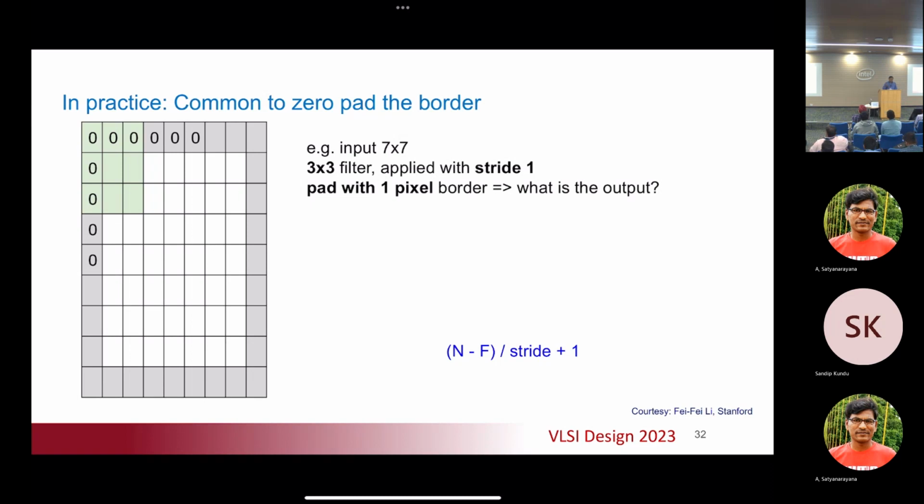So including normalization, including nonlinear activation, and including the Softmax layer, the very last layer of computation, which I didn't describe, I'm going to describe that. It's about 10% of the computation. So if you want to accelerate something, this is what you want to accelerate. Okay. If you have more resources, you would of course accelerate the other things. But if you have some resources to accelerate, that's the first line that you're going to accelerate.